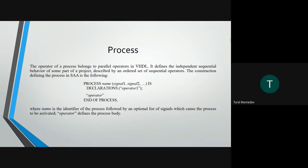And also we have a process in VHDL. The operator of the process belongs to the parallel operations, and it defines the independent sequential behavior of some part of the project, described by an ordered set of sequential operators.